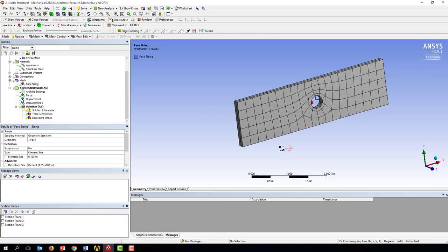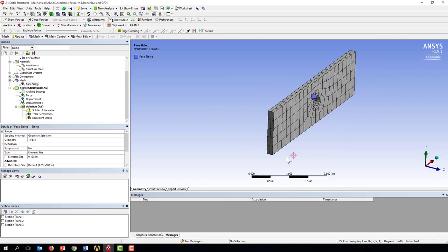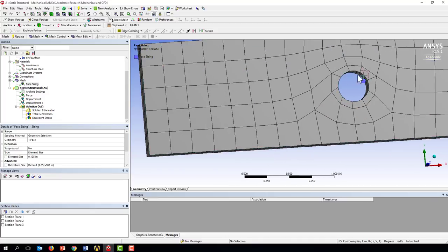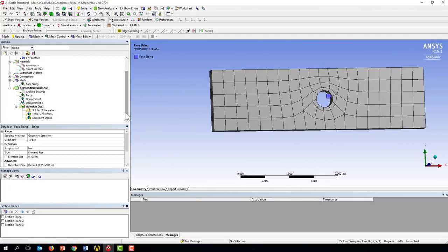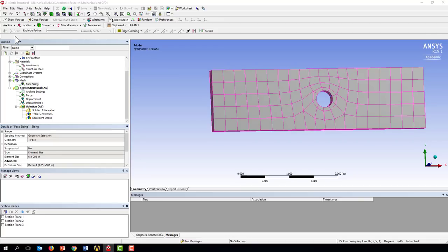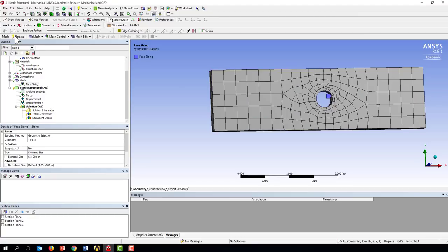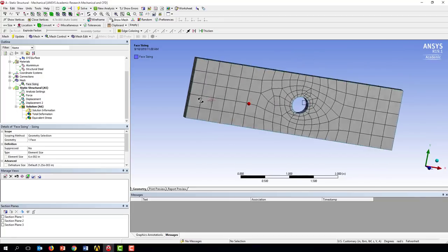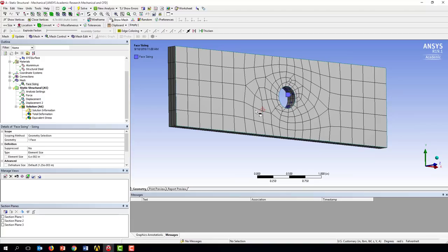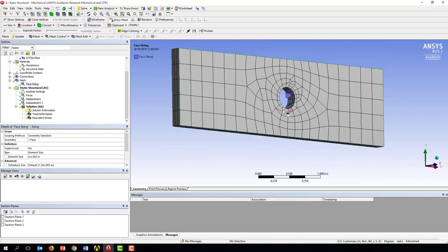Okay. So you can see, to do that face shadow, it's made these thinner this way, so I've decreased the aspect ratio, and then it's made a little finer mesh around the circumference. I could adjust that and say I want to go to 0.06, and let's update. Okay. So again, a little bit finer, and it's shrunk on the other dimension as well. And this goes back to how it meshes with brick elements, that it has to do both.